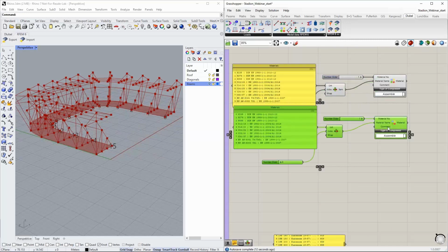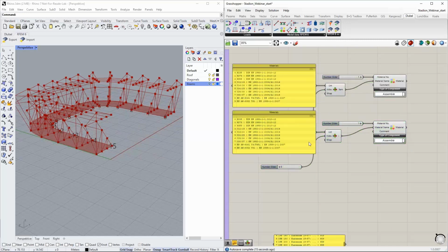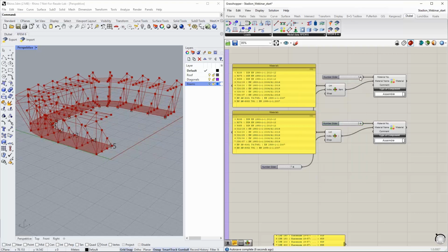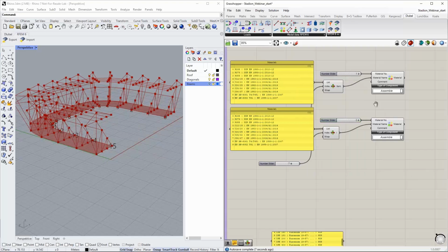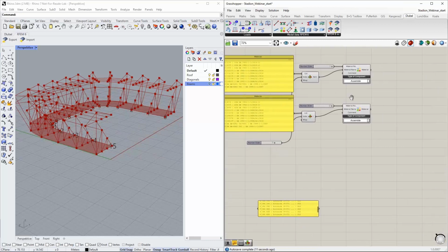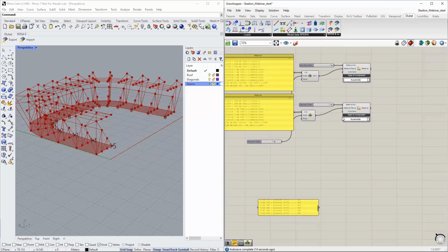Let's say I need 2 materials. I can use copy paste, just modify the slider here. Let's say I want also a concrete C30/37, and I also have to modify, of course, the number here for my material. You should not assign the same index multiple times to objects. This can cause errors in RFEM 6, of course. All right, so now I created 2 materials.